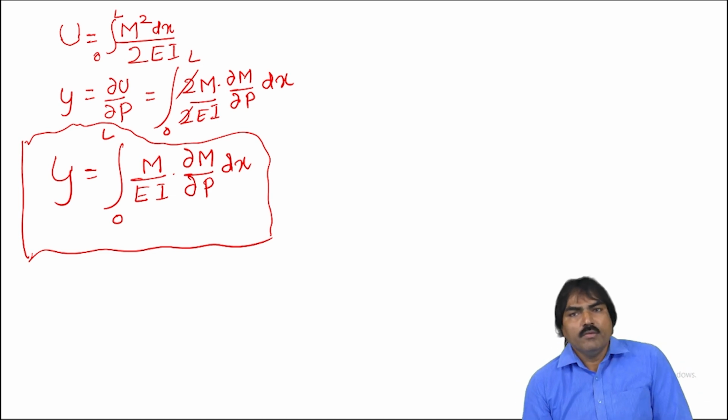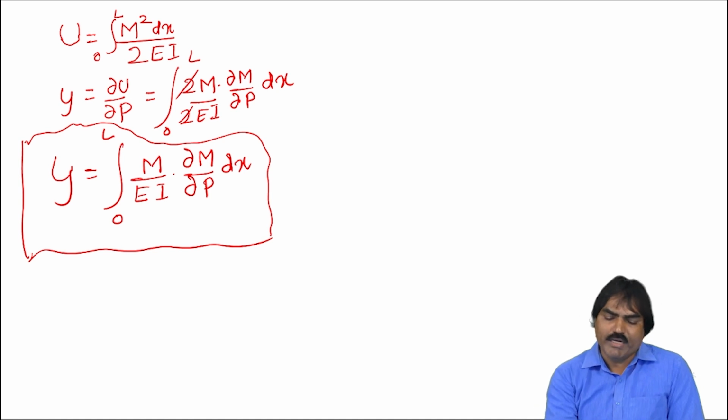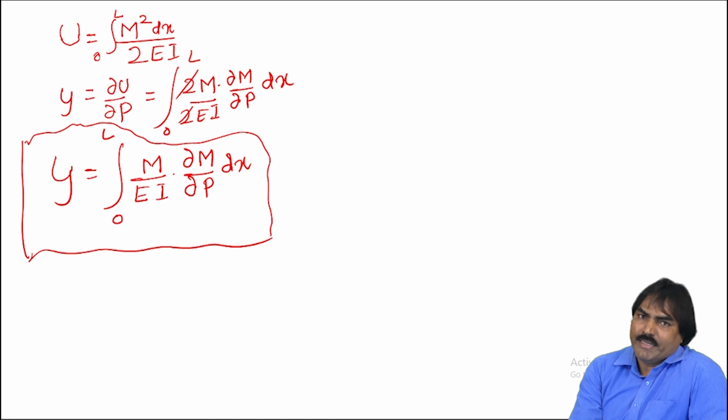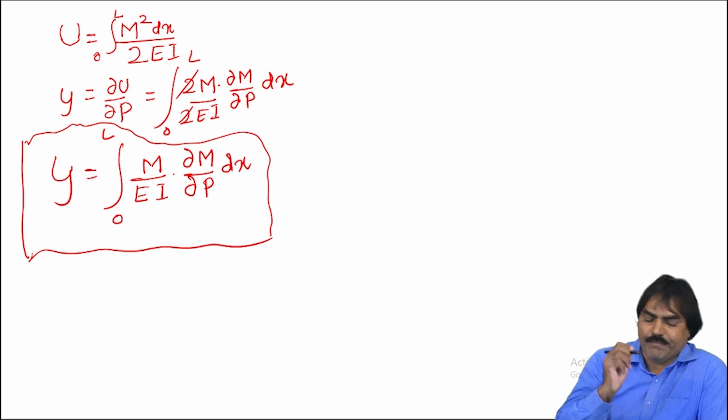Okay. Once you know the moment, you can differentiate the moment with respect to the load at that point so that you will get dou M by dou P. Substitute that and then carry out the integration, you will get the deflection.